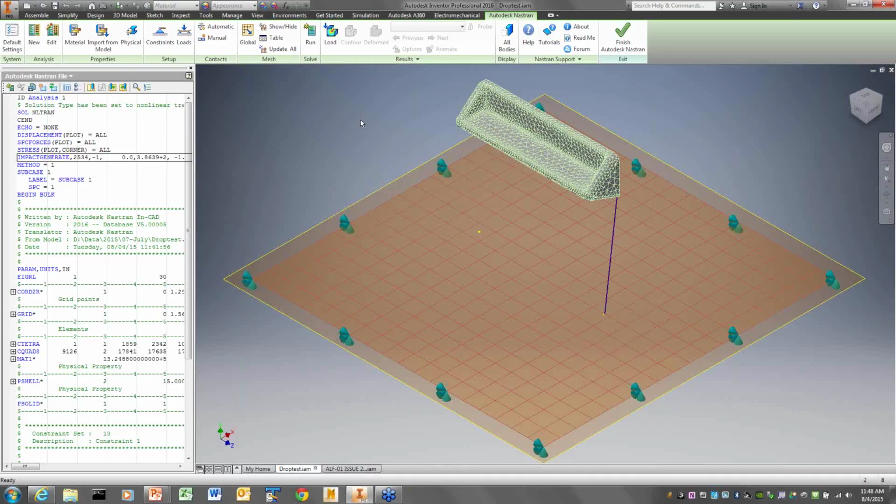And what usually happens is it yields, and you end up with your little cube with little dinged corners on them. And your phone, if you're drop testing your phone unintentionally, you'll see little dents on the corners and little dings, and a lot of that is because you're going to see a lot of plasticity right at the impact point. So that's the kind of thing I would expect to see when I do a drop test. And I would ignore super high stresses at the impact point, but I would look at the zone of plasticity and see whether it makes sense.